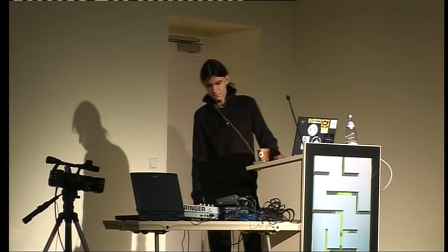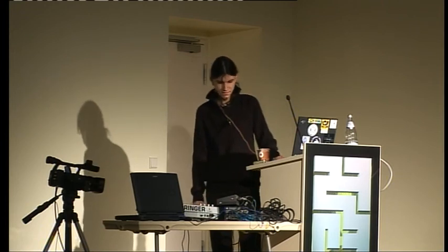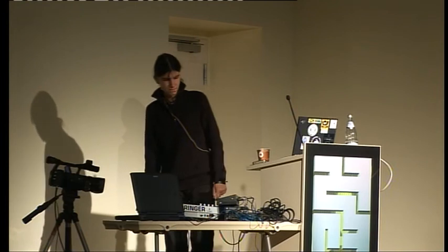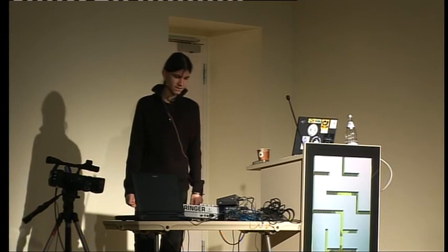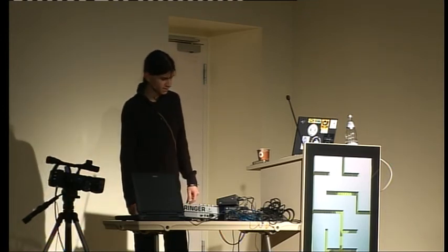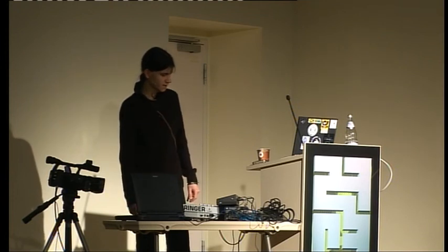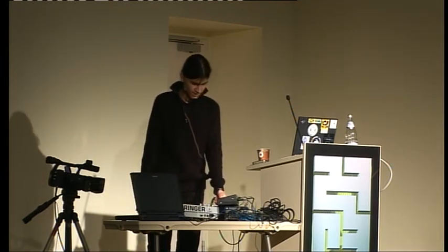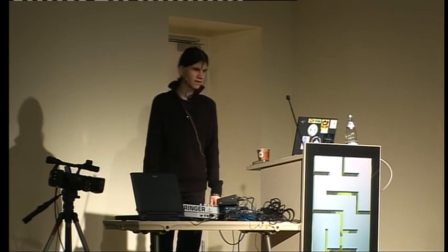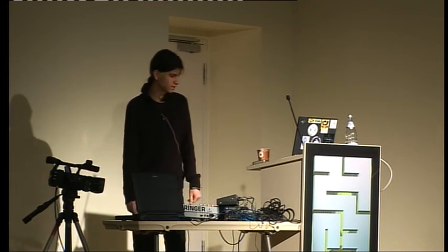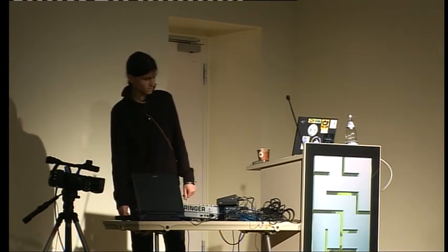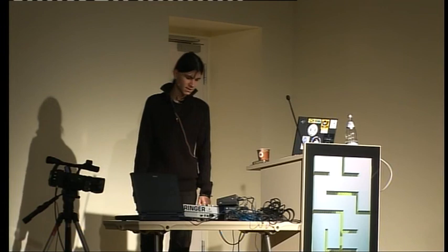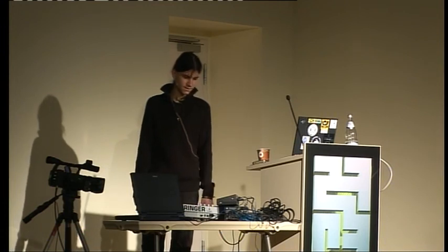What you can hear in this example is a synthesizer based on the Commodore SID synthesis, but it doesn't include any SID in it, everything is emulated in software. So there is a microcontroller in it. In this case, this is a Parallax Propeller microcontroller running at 80 megahertz. No external components, and the SID, the Commodore sound interface device, is completely emulated in software.